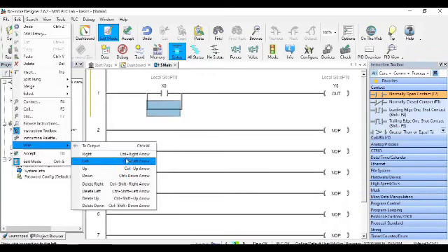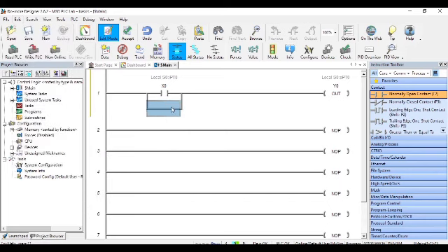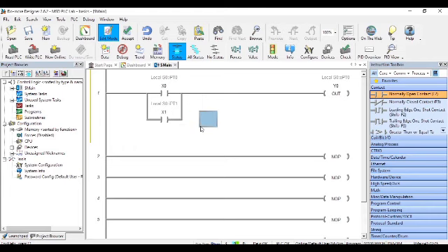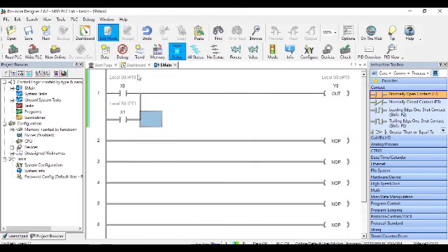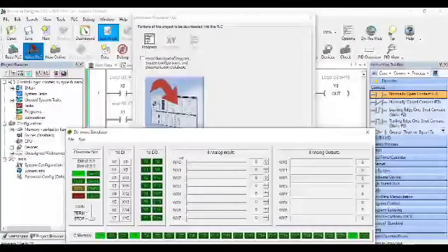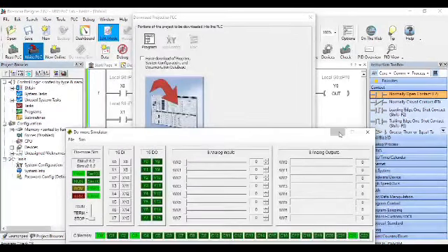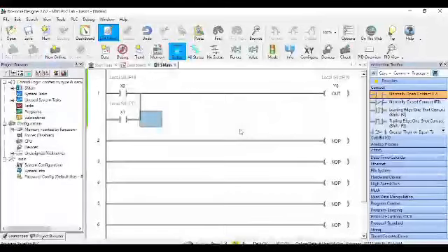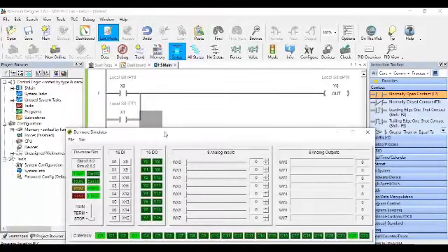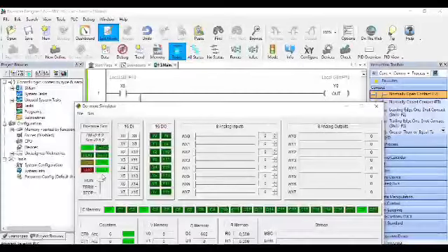Now if this is inconvenient for you, you can simply remember the shortcut keys. It's quite simple. You can press Control and the arrow keys on your keyboard, so that's much easier. Now I can simply drag another input at this point, and I will call this x1. So I'll accept the changes, nothing happens, so no errors. I'll write to my PLC making sure this is off. I'll click OK, no errors. I'll click this and I will run this.